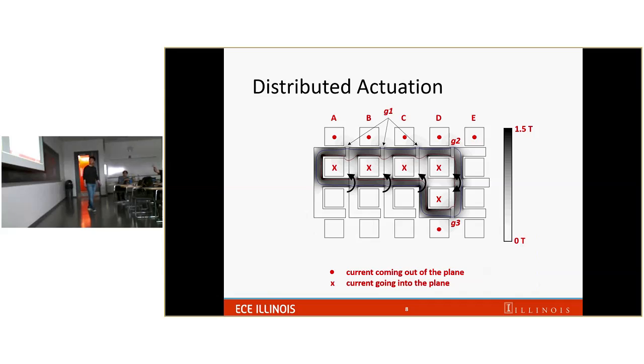Is there a reason why you wanted an additional loop where you activate two coils, D and G3, instead of just going to the middle, instead of ending it at ABC? Because if I do this, I can firm this position. If you want to hold it in a neutral position, you have to activate both coils. Yes, because if I don't excite these coils, it'll be loose and move wherever. So if I want this structure to be firm, then I should excite both of the coils.